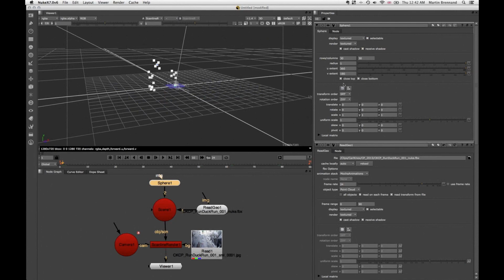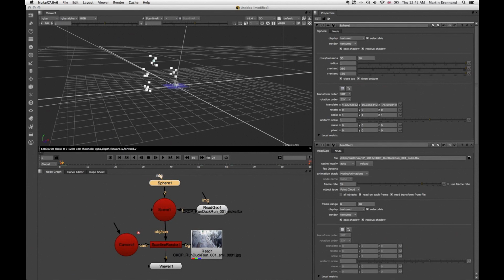And the way to do that is we've got in the sphere panel this snap menu. So if we click the snap menu, you just choose the selection option that you want. In this case, I only really care about match selection position. But when you're dealing with actual orientation, you want to do all three, either the size, orientation, and position, or the position and orientation. And this is probably the most common one you'll want to use. But in this case, because it's a sphere, I'm just going to select match selection position. And then that will pop into place over here.